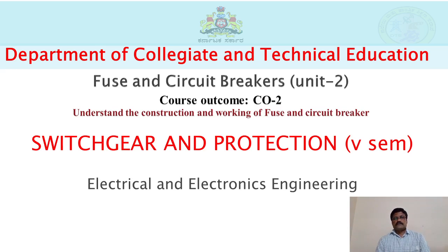The maintenance of an oil circuit breaker requires checking the contacts and also the dielectric strength of the oil, because an oil circuit breaker mainly consists of two contacts, one fixed and another movable, enclosed by a metal tank and immersed in oil. So the two important parts are the contacts and the transformer oil.